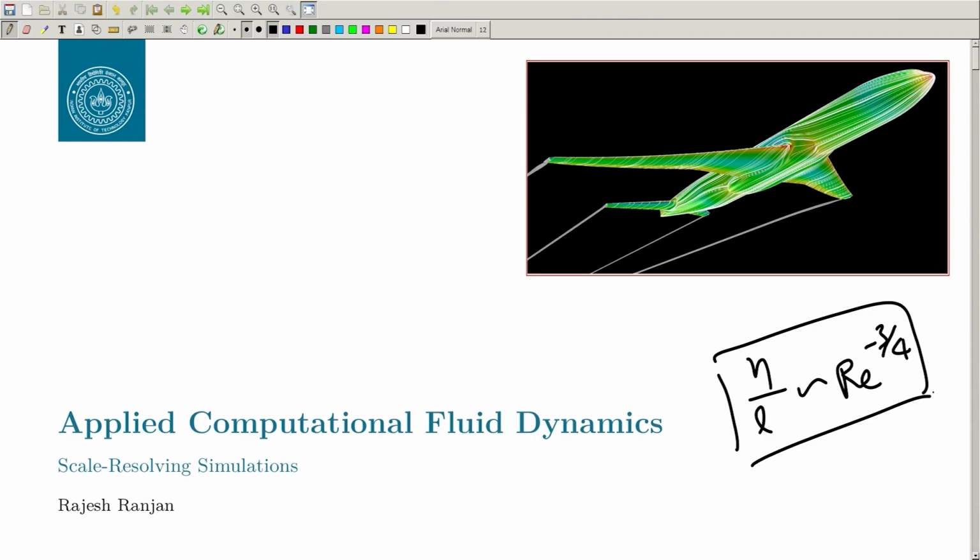That means the viscous forces are so high that the eddies can dissipate. By considering those assumptions, and different velocity and length scales for the largest eddy and the smallest eddy, we arrived at this number.